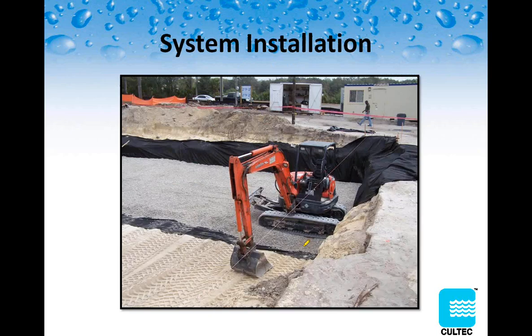And taking you through a typical installation, what you would do is excavate a big hole to the depth and length and width that was designed on the drawing. And you would lay down your filter fabric down the sides and the bottom. And then you would place your base of stone down. Typically it's 6 inches, but that can be increased to get extra storage volume.